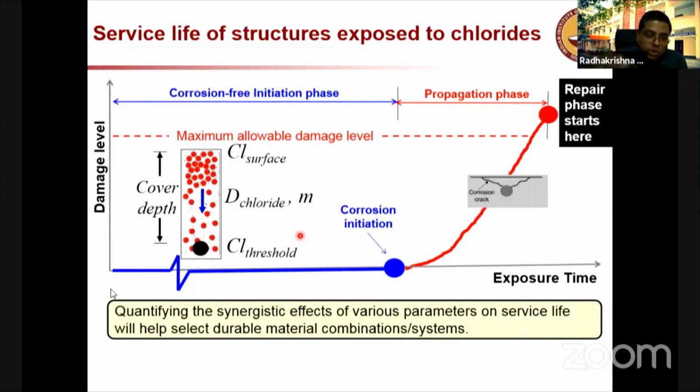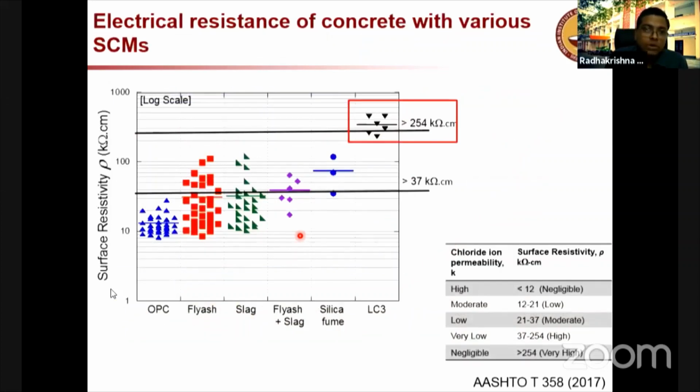So even if I'm showing you in the remaining presentation some chloride thresholds going down or decreasing, you have to really think about the synergistic effect of that, because even if a chloride threshold is less, there may be other factors which help in enhancing the service life. That has to be taken into account.